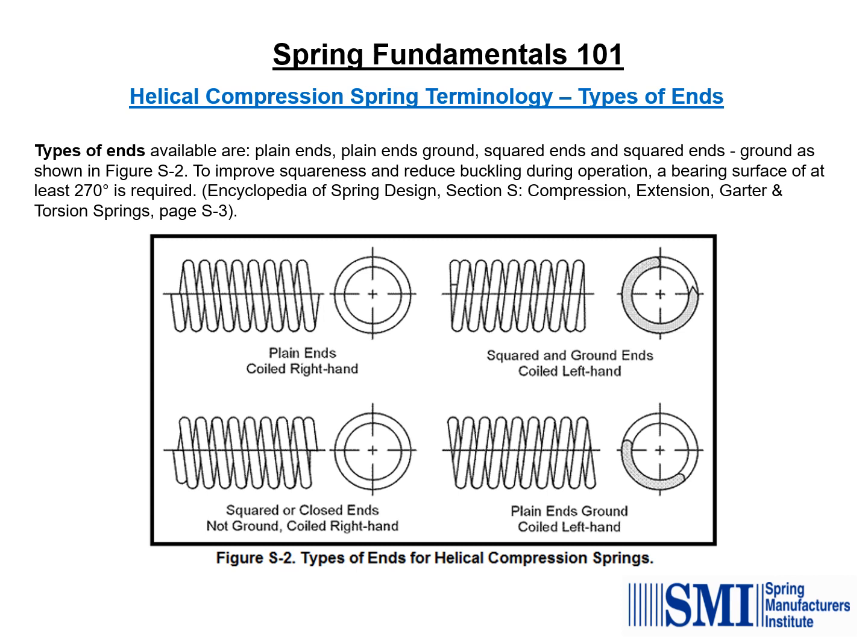Too much grinding can result in thin sections. Squared ends only are preferred on springs with small wire diameters, 20 thousandths of an inch or less, or a large index, something greater than 12, or a low spring rate. Squared ends cost less to manufacture than squared and ground ends. On a side note, it is not common to have open springs with ground ends.